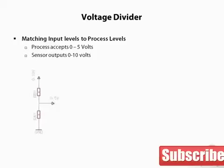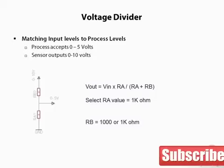Here is our circuit diagram, again, except V in equals 0 to 10 volts and V out is equal to 0 to 5 volts. Looking at our equation again, V out equals V in times RA over R total. Since our equation is ratiometric, mathematically it doesn't matter what the exact values of the resistors are, only the ratio of them. So for now, let's arbitrarily choose RA equal to 1 k ohm. Then solving for RB, it is also equal to 1 k ohm.